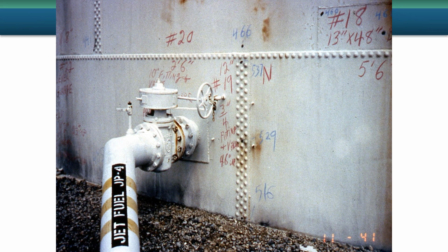Here's a riveted tank. There's typically nothing wrong with riveted tanks. The steel's often quite good, but sometimes it isn't. It's a crapshoot, so you really do need to do physicals and chemistry if you're going to work on a tank like this to determine that it's got good weldability characteristics, reasonable toughness, and not too many tramp elements, excessive sulfur or molybdenum that would cause brittleness. But like I say, many of them are quite good, and people seem to have a prejudice against riveted tanks.